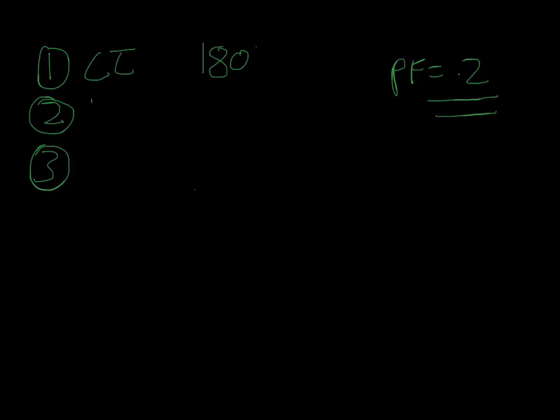Another thing as well is the VT or the PT. Keep that in mind as well. You want to make sure you check the connections on your PT or your VT, and make sure that they're correct, including the polarity on those.